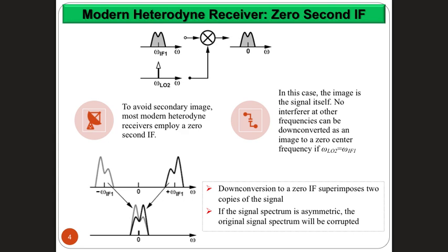You can see that it has actually two bands appearing, right? Okay, so anyways, when you bring the signal down, those two don't look the same. They are mirror images of each other, right? And when you add them, you end up with something here that does not look like the original signal. So the signal itself becomes an image of itself, which means that it will self-interfere and self-corrupt when you bring it down to zero frequency, okay?